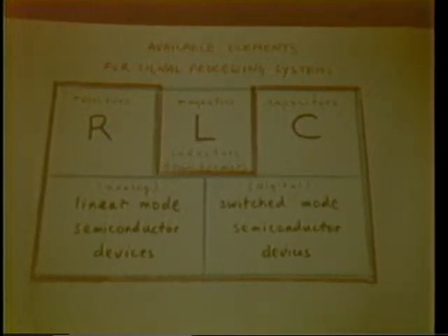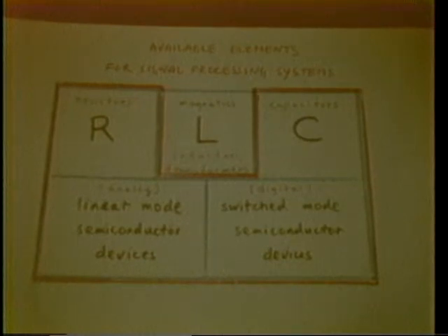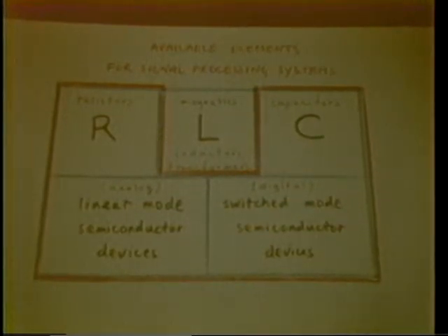Magnetic devices don't fit onto the ICs very nicely. They're totally incompatible in physical structure with the extreme degree of miniaturization which we can accomplish now in ICs, integrated circuits, LSI and VLSI and so on. In fact, signal processing design engineers will go to great lengths to avoid using any magnetics, even if they should need the function of an inductor.